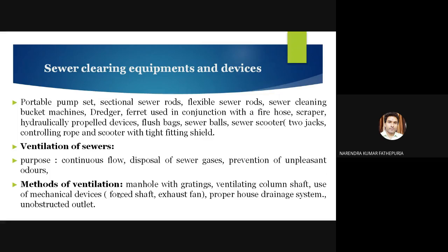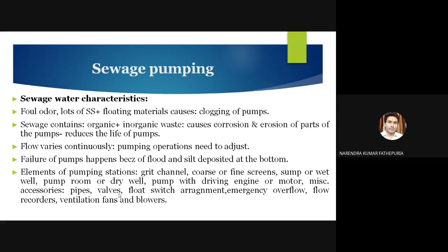Ventilation of sewers is for continuous flow, disposal of sewer gases, and prevention of unpleasant odor. These are the objectives for it. Methods of ventilation: manholes with gratings, ventilating column shafts, and use of mechanical devices. These are the various methods.